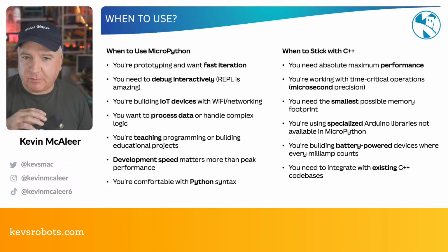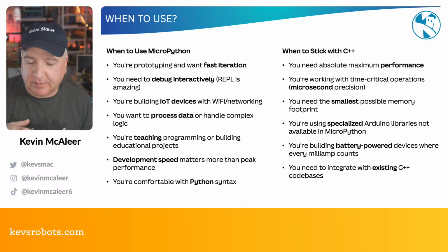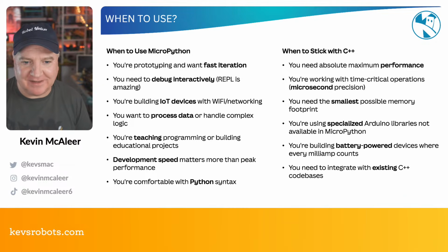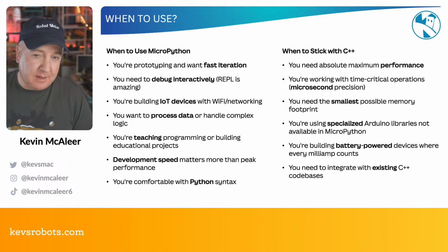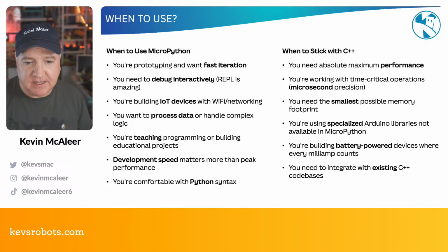So with MicroPython, there is an overhead of the interpreter, and objects in memory take up a little bit more space as well because they have things like reference counting and so on. We can have a look at what all that means later on in the demo. If you're using a special Arduino library that's not been ported to MicroPython, that might be another reason to stick with C++. And if you're using some kind of battery-powered device where every milliamp counts, then again, you might find that C++ is a bit lighter on power usage, just because it doesn't have to have all that interpreter in the background. And if you need to integrate with existing C++ code bases as well, that might be another reason to stick with C++.